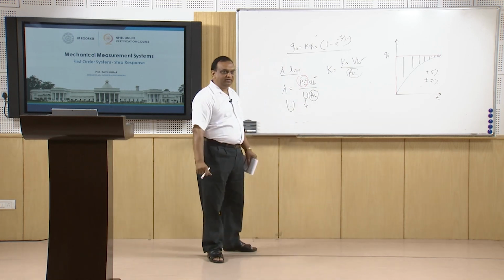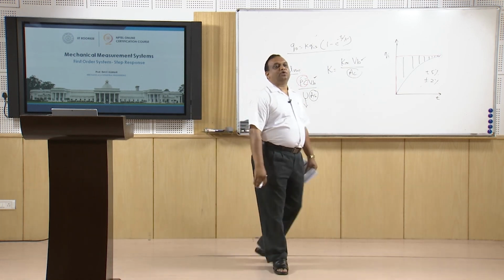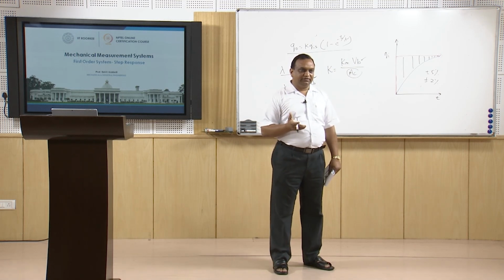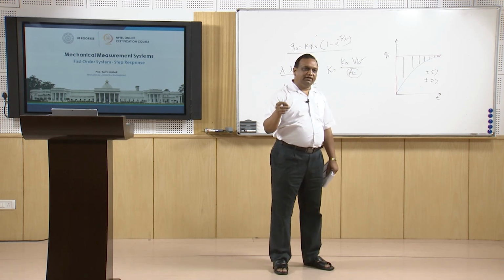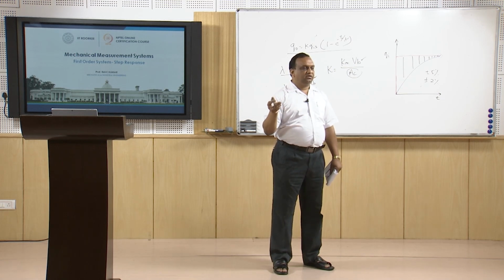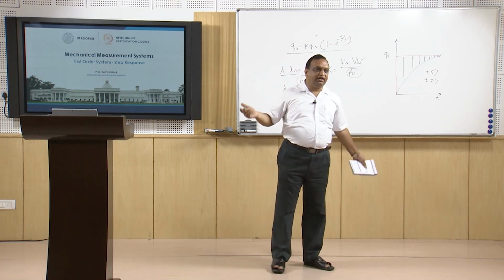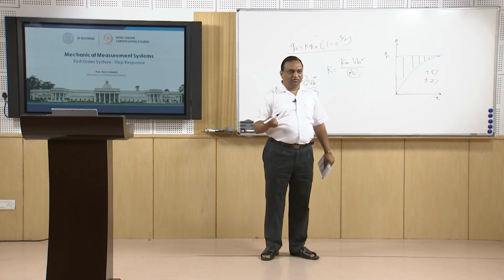Now, this is important. We cannot control the overall heat transfer coefficient, but we can always assess it. Suppose the thermometer is measuring some high temperature fluid which is flowing in a pipe. In that case, U will be high. When the thermometer is measuring still air, for example, air in this room, then U will be low.